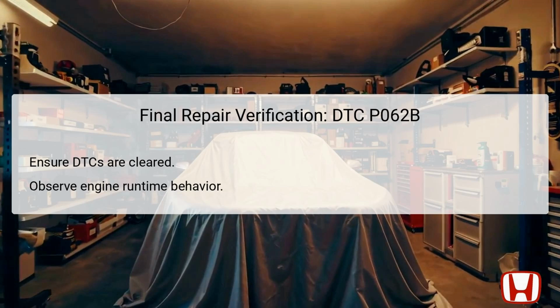The final repair verification step involves confirming that the DTC P062B has been successfully cleared and that the engine operates normally following the applied repairs. This involves rechecking the DTCs with your scan tool to ensure that no error codes remain active or pending. Observations during engine runtime behavior are crucial. The engine should run smoothly without performance hiccups, and the MIL should stay off during operations.